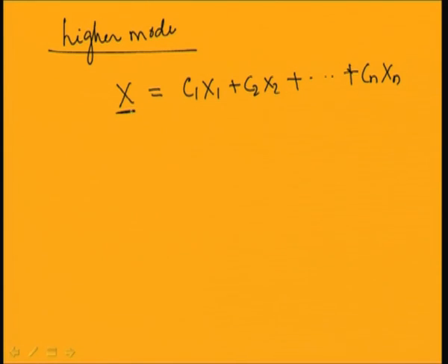So if the assumed mode contains the first mode, then the resulting vibration, or the natural frequency or eigenvalue that we want to obtain, will lead to the fundamental frequency only. So to find the higher mode frequency, we have to make this C1 equal to 0 in the resulting vibration. To make C1 equal to 0, we may use the orthogonality principle.